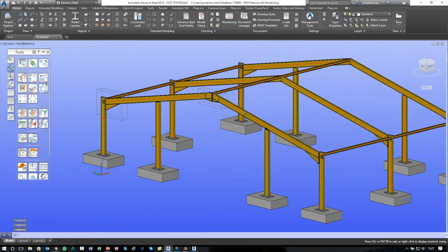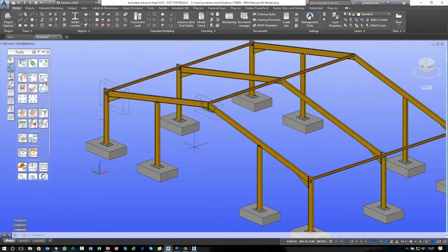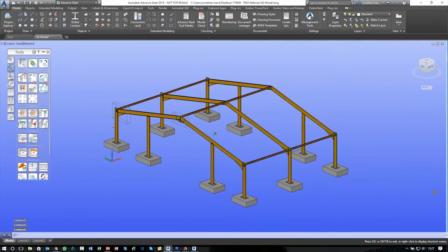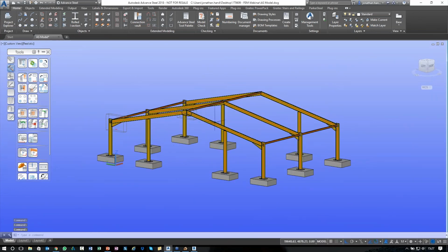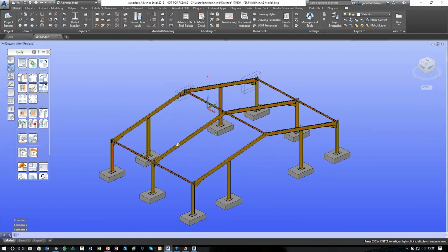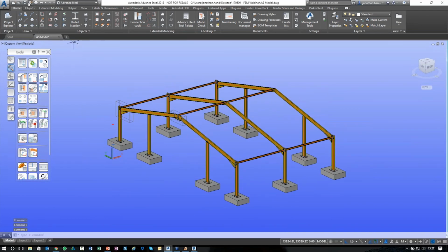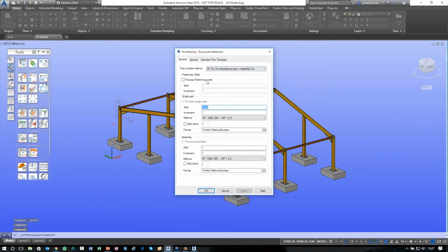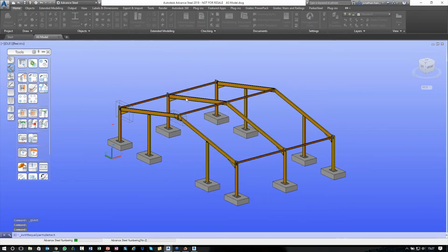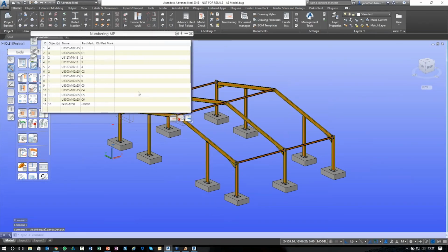I'm just going to let Revit whir away. So this is where I can synchronize between the software. So I'm going to load my file. You notice that it is timestamped 1527, so 1 minute ago. And this looks through the synchronization file. So what we exported, it's then checking to what we changed. And you can see that there's quite a lot of things that have updated. So some of the columns, some of the beams have changed, and this is where we've added joints.